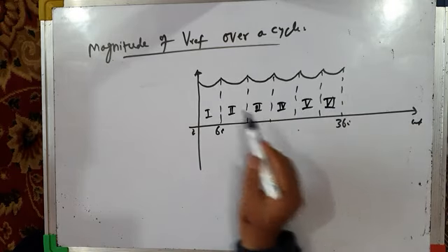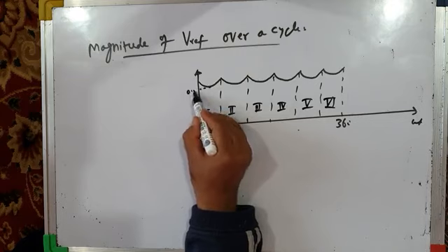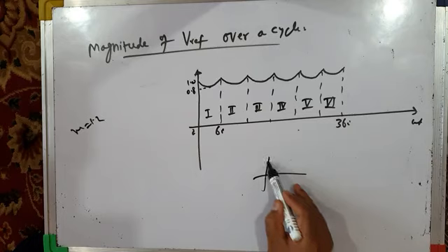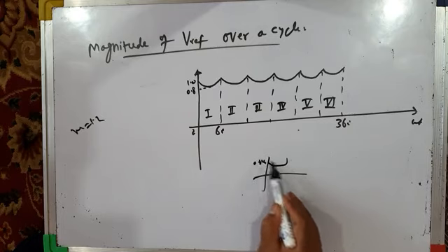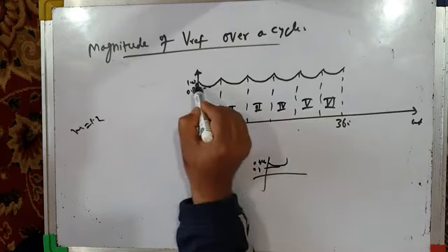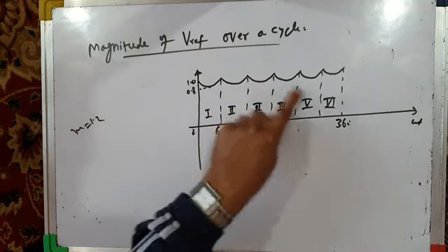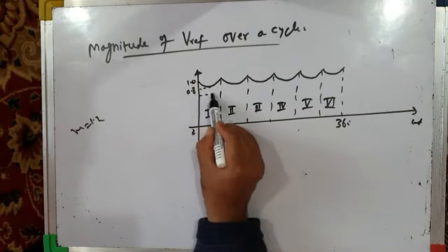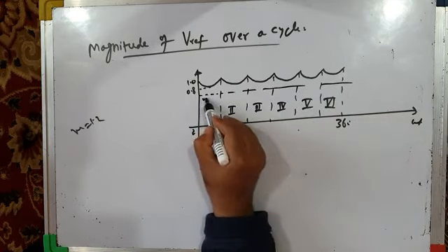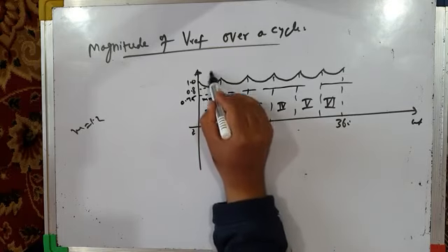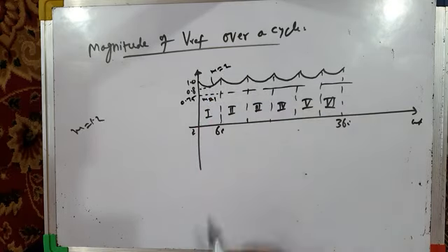Fine. So this is 0.8 and this is 1. And for m equal to 1.2, it was like this. It was varying from 0.866 to 0.8. Now its amplitude further increases from 0.866 to 1. But you can see it again varies. It's not constant. It is constant for modulation index equal to 1, for example, 0.75. But this is for modulation index equal to 2. It is not constant. It is varying. But its peak value has further increased.